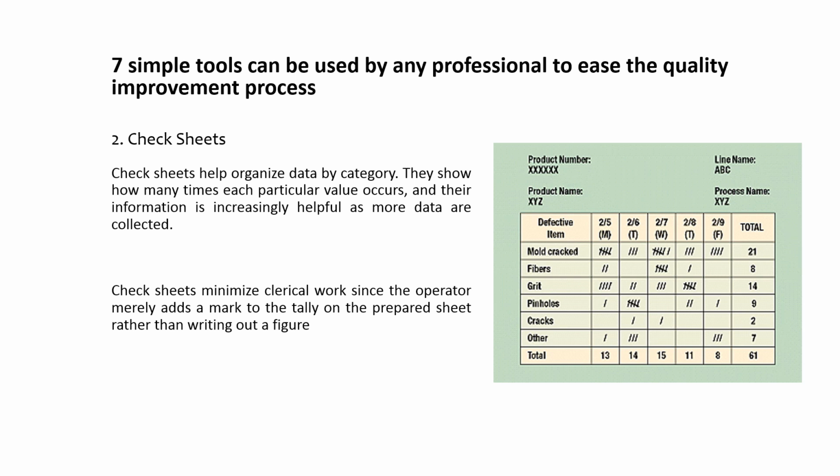Second one is the check sheets. It helps organize the data by category. The check sheet example shows a list of molded part defects on a production line covering a week's time. One can easily see where to set priorities based on results shown on this check sheet. Assuming the production flow is the same on each day, the part with the largest number of defects carries the highest priority for correction.